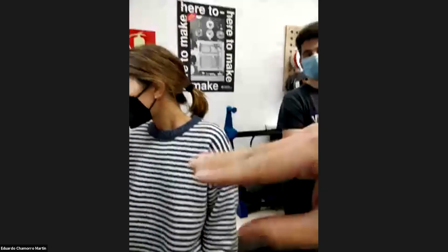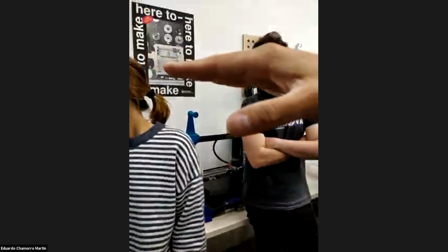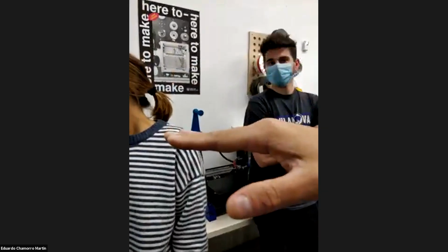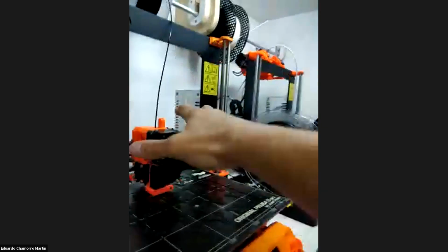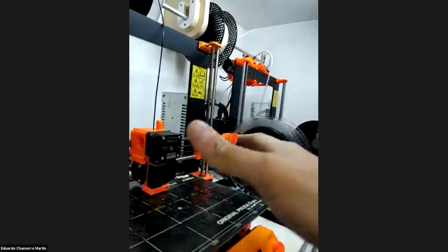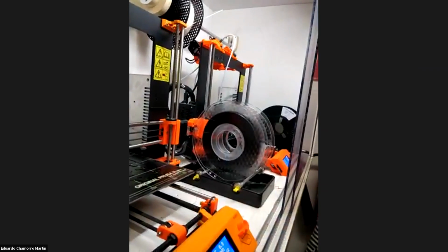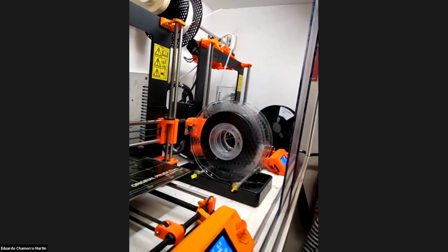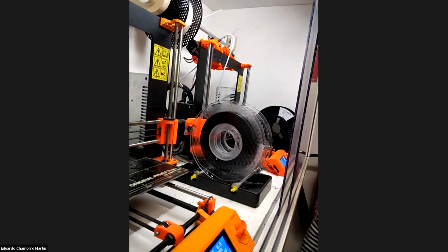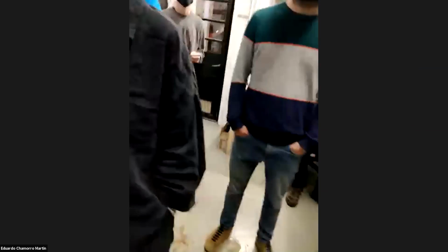The Z is not moving up and down all the time. Actually it's just moving a little bit. And we have something that is gravity. So actually it's being pushed, because this is heavy, all the time to the bottom. But in case you are really printing in 3D, moving the Z all the time, that might happen, you will have a lot of backlash. Actually, you can see from the printing quality that is set.